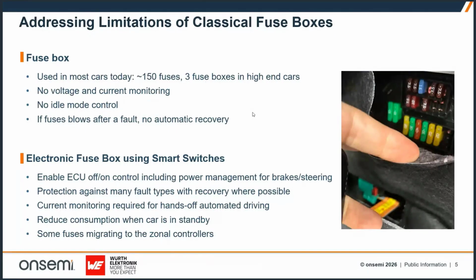Let's say the light system normally takes, I don't know, 400 milliamps. I'm picking numbers here. And then suddenly it's only doing 200 milliamps. Why are the lights failing? Why is there suddenly less power? That monitoring can say, okay, you've got a problem. You've got to hand back to the driver in a controlled way. You can't just say, sorry, I'm giving up, you've got to take over immediately. We put it in a safe state, then hand over.